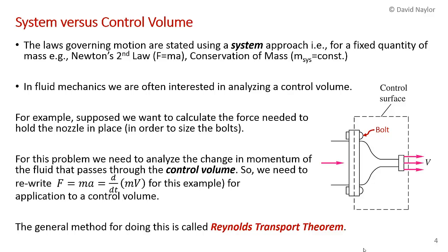And also if you think about the conservation of mass principle, if you have a fixed amount of mass, as that fixed amount of mass undergoes changes, the mass remains constant if we neglect relativistic effects. As I already mentioned, in fluid mechanics, we're more interested in drawing control volumes and looking at flows in and out, so we're interested most often in analyzing control volumes.